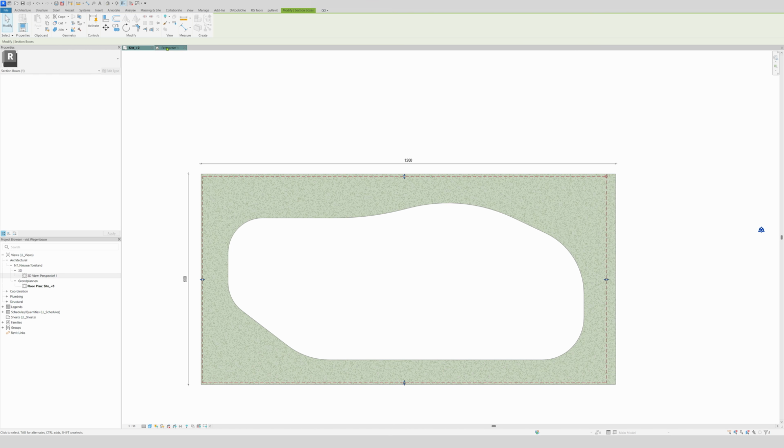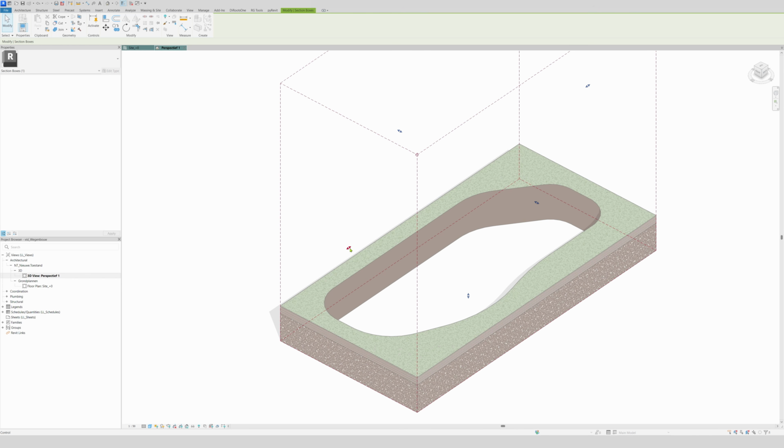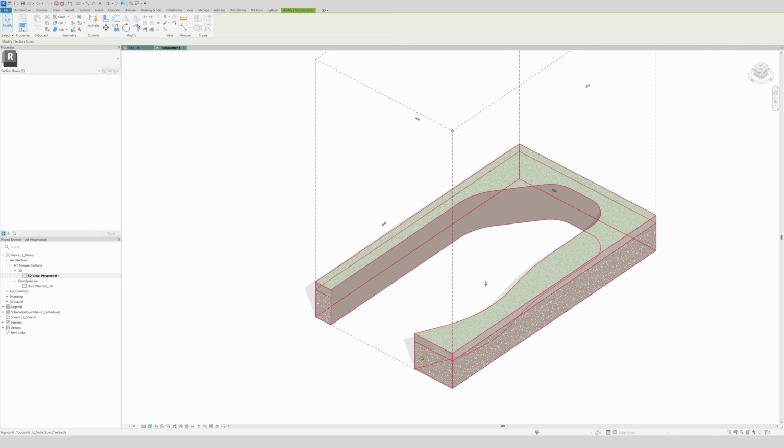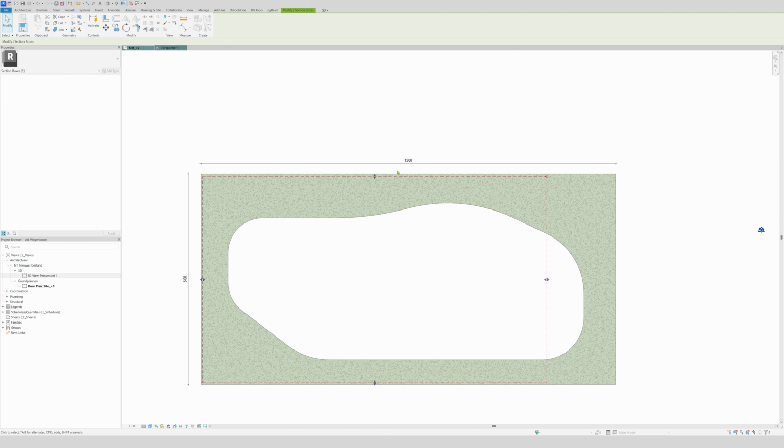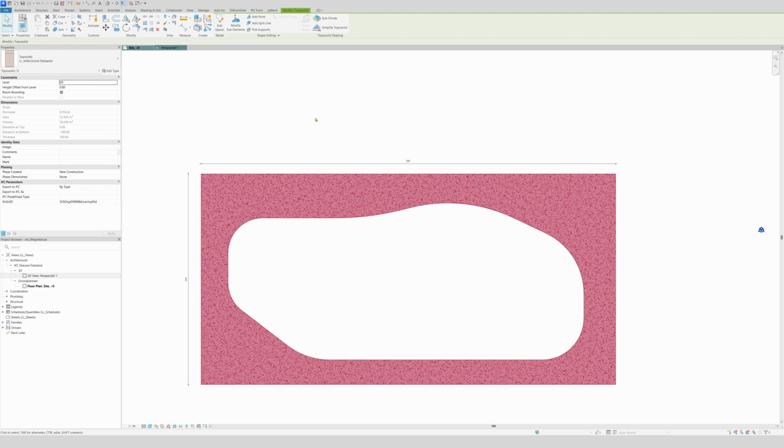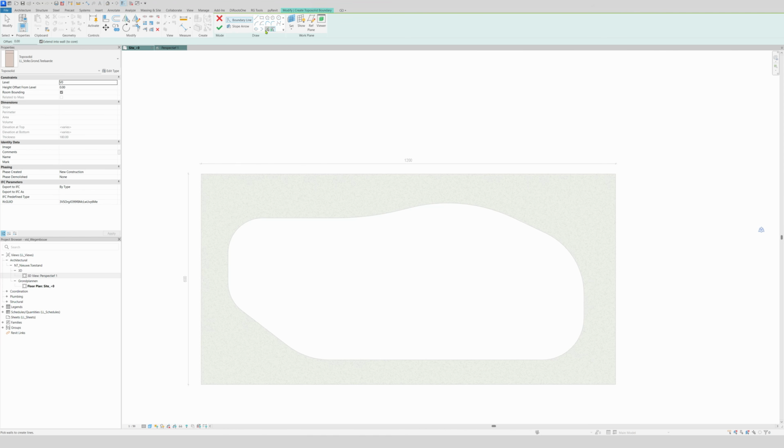Now what we are going to do is make the base, so the inside of the infiltration pond. How are we going to do that? Very simple. We're going to use Create Similar, and then we're going to use an offset of 80, and now we're going to make our pond like this.